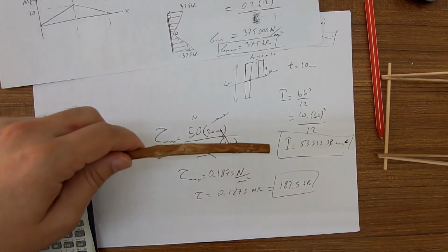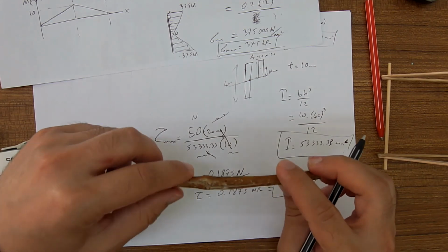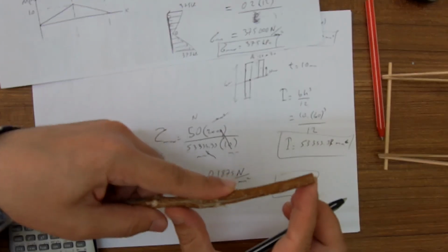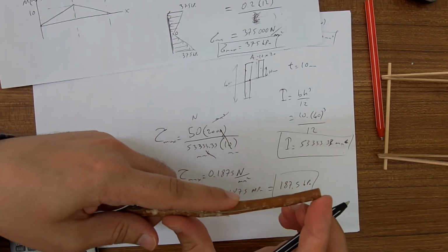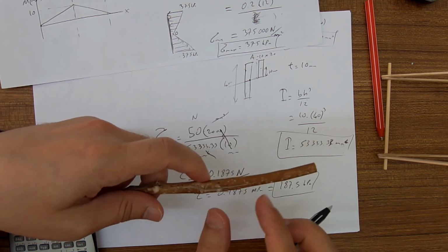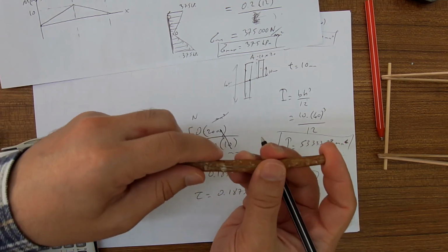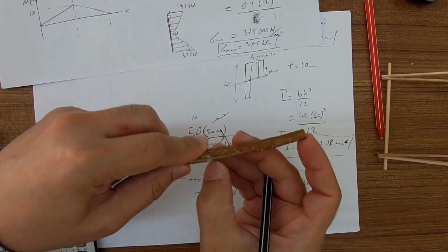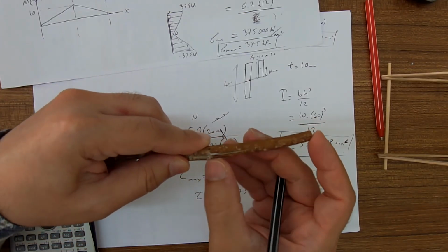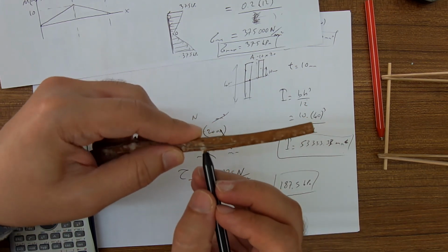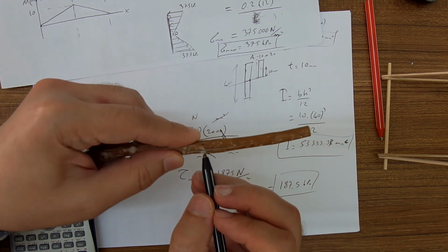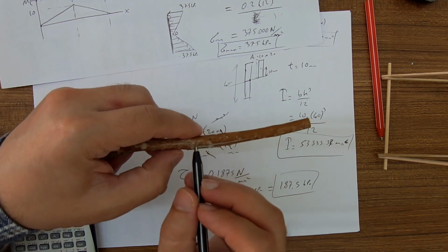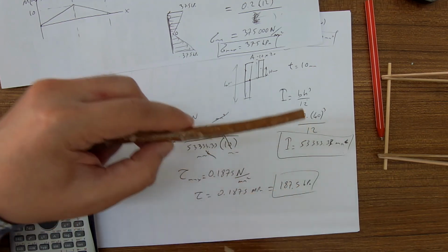But for a wood like this, you see that the shear failure occurred before the normal stress. You can also see the effects of normal stress. You see the fibers have separated at the outside of the section, but most of the failure is due to the shear.